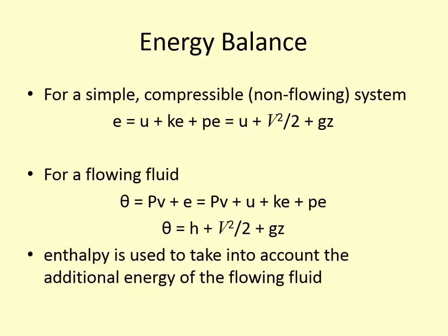So why is there an enthalpy term in an open system? Well, it's because of this flow work. We just derived that here. We just showed that it takes into account the idea that this fluid now has energy associated with its movement. Just like boundary work, but now it's within the walls, inside the system itself.